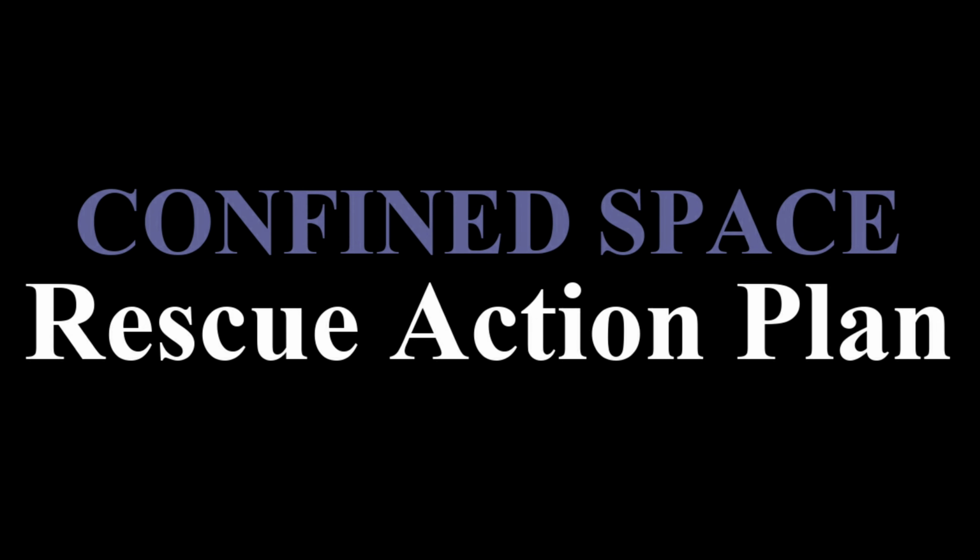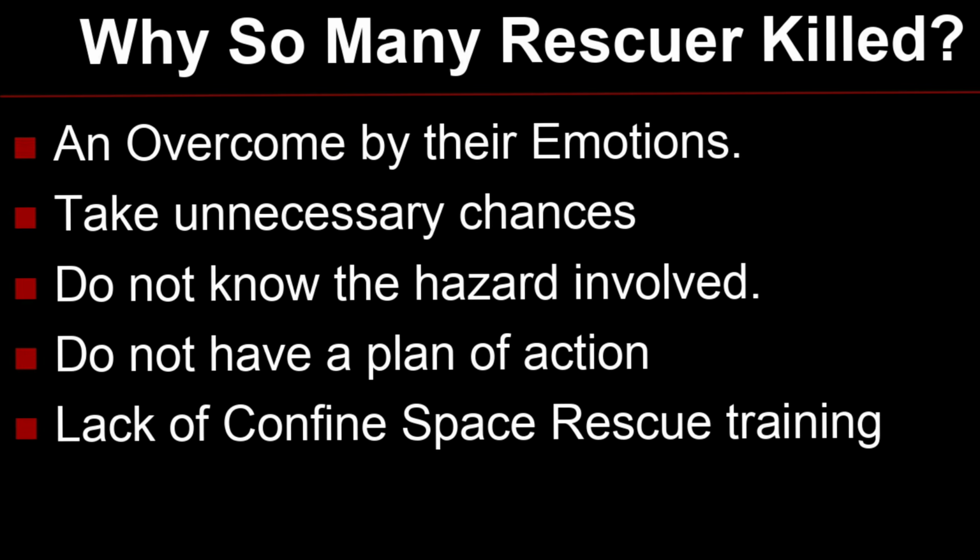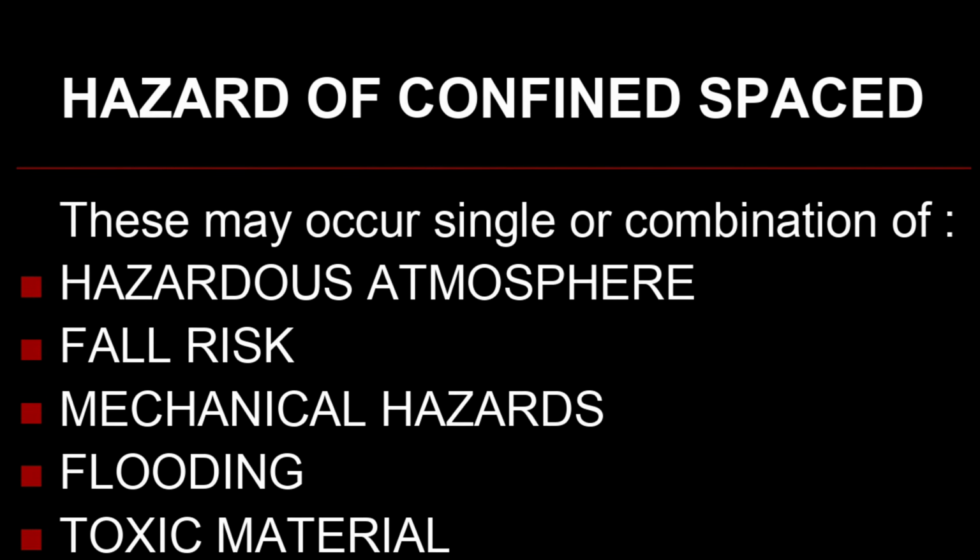Confined space, rescue action plan. Why are so many rescuers killed? 1. They are overcome by their emotions. 2. They take unnecessary chances. 3. They do not know the hazards involved. 4. They do not have a plan of action. 5. Lack of confined space rescue training, etc.